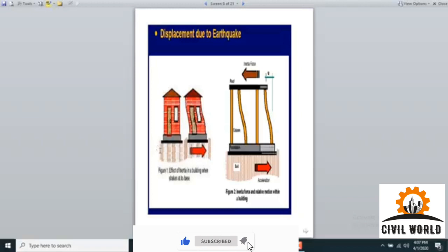And you can see the wave is passing below the base. Once the wave comes right below the base, it imparts some acceleration into the base of the structure, which then transfers it to the upper side, or the superstructure, known as the story shear. So here we have base shear, and here we will have story shear.